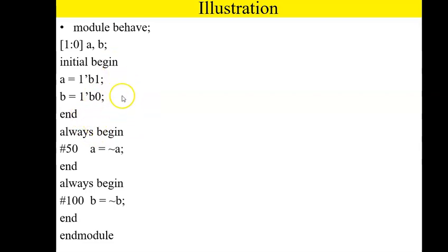We have defined these things. These are useful during the simulation actually. So A and B are defined. Now the behavioral model: always, no condition, nothing. Begin. #50. This always indicates, remember, the time delay. We'll understand this in the next classes.